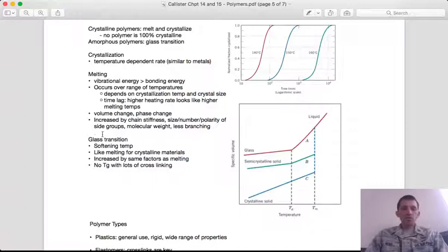You can also move around this melting point by shifting the balance between bonding of the polymer chains and thermal energy. If I want to move this melting temperature to higher temperatures, then I need to change the chemistry of my polymer to make it more attracted, more bound, or more impeded, and that will require more thermal energy to overcome that chain hindrance, we call it.